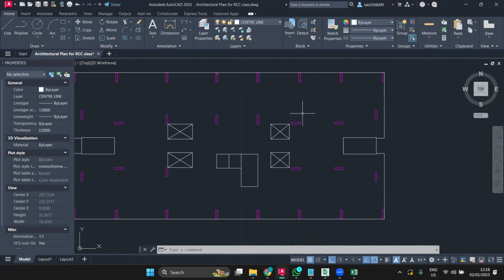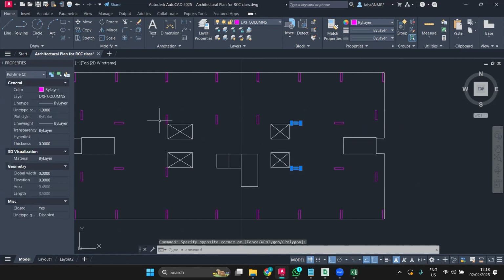These two columns, I should make it like the left side, then it will become similar. No, I didn't understand. These two columns, if I make them vertical, then it will be like a mirror. Just now I told you, because all the columns are placed at 90 degrees, you will have more stiffness in the shorter direction. In order to get the longer direction, it is good that you have some of the columns.